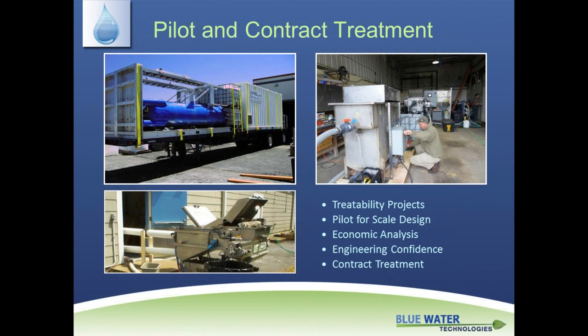Usually the next step after a bench scale is to pilot, to demonstrate the process in line, a continuous flow treatment system. So pilot testing is sometimes needed following bench testing to obtain scale operating parameters, chemical usage, and energy requirements as well. A bench scale makes a life cycle cost estimate possible, but piloting can really add the precision needed for an economic analysis and get much closer to the real mark to get into a project.